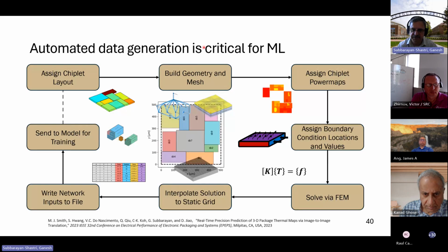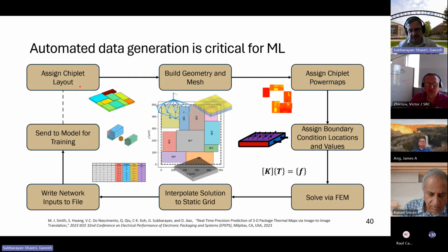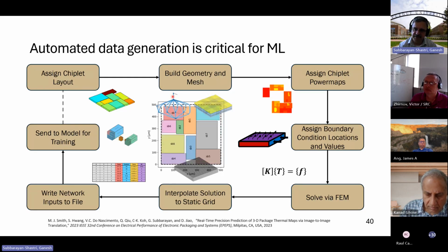In this particular study, what Dan and I were able to do, we had developed, in my group, a finite element code, which could automatically describe any complex three-dimensional layered structure like a 3D package. And then we could apply boundary conditions and analyze it. We were able to automate that process, and that required some data structure to represent three-dimensional layered structures, which was a topology graph.